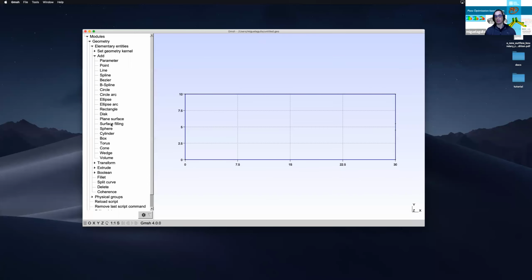Right now, I do have points and lines connected to those points, but I have not defined a surface. And there's many ways that you can do this. Usually, I use these plane surface options. With this option, I basically select my 2D geometry. And now I can click E, and then that ends the option. And as you can see, I have defined my plane surface.